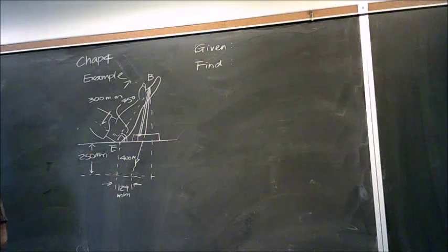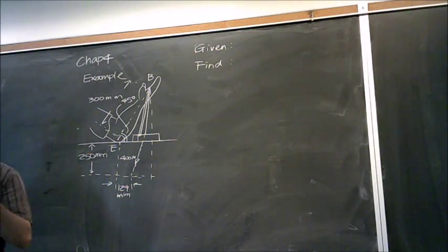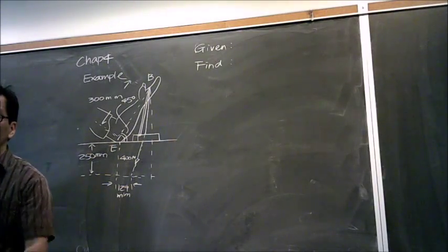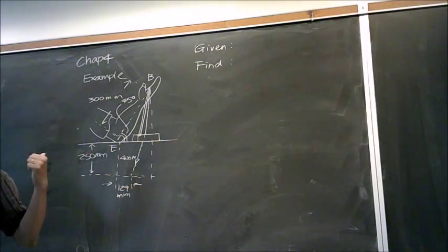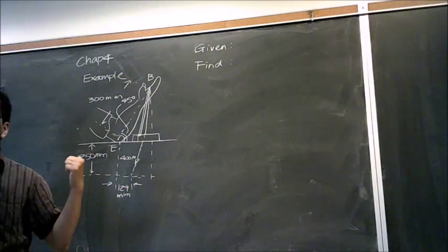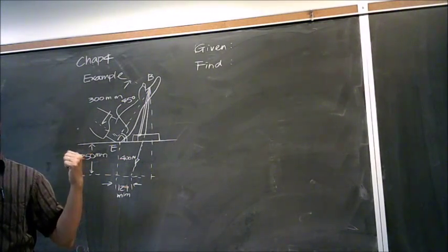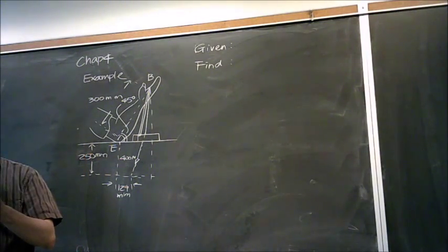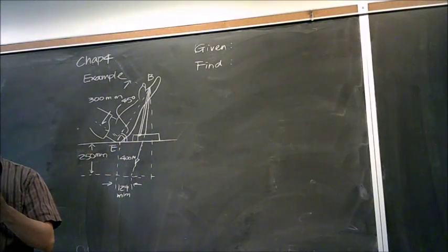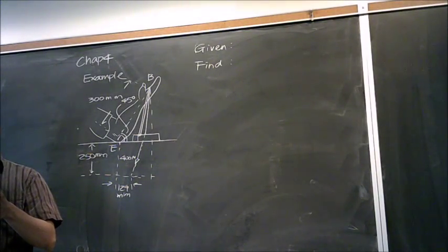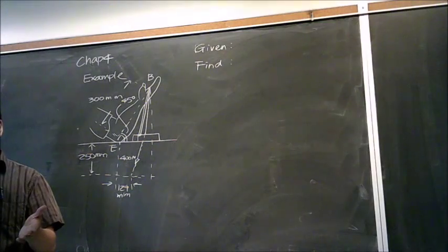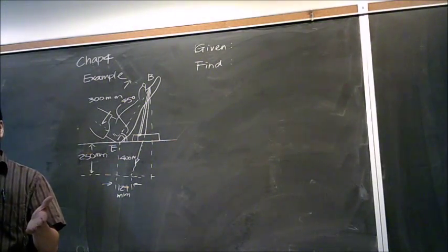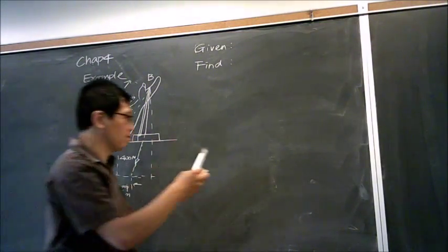Okay? But way before we define those things, one thing you need to determine is this system an English unit system or is a metric unit system? Okay, so when it's a metric, be sure when you see the force or anything, you don't divide that by 32.2 or whatever, okay, because they are not the same.